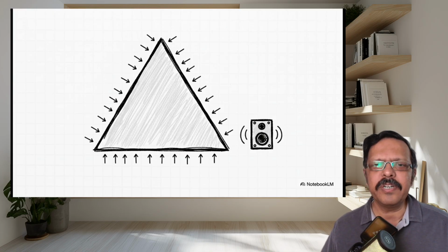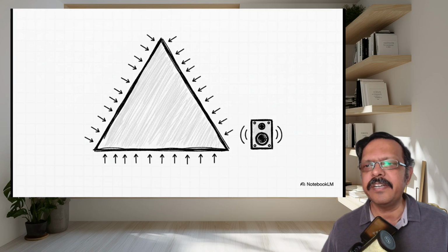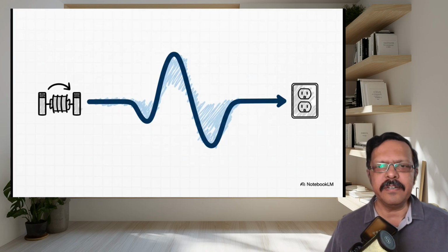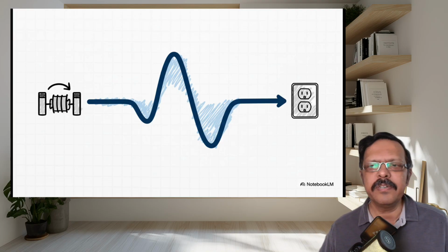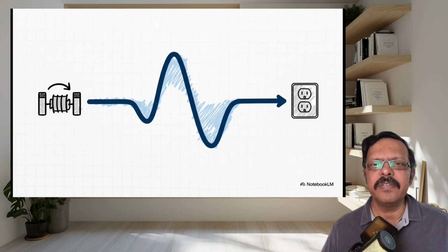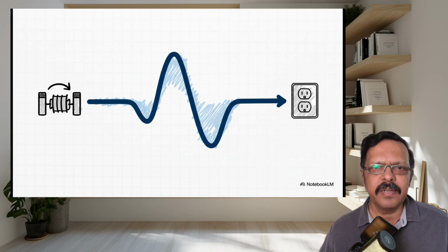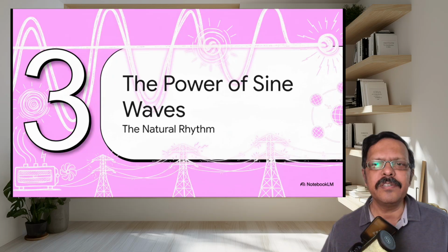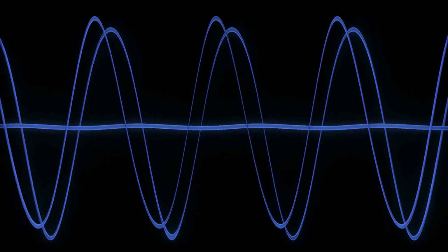Now let's look a little bit into what an AC signal is. Most of the world's information, audio, video, radio, everything, rides on an AC signal. AC is alternating current. Unlike DC, which is a constant current, AC signals vary with time. The most important one is the sine wave, which is a smooth, continuous waveform. There are other AC signals as well, but the one of most interest to us is the sine wave. So why do we prefer it? It's incredibly easy to generate, transmit, analyze, and consume. Power systems, radio communications, and even audio all rely on sinusoidal waveforms.